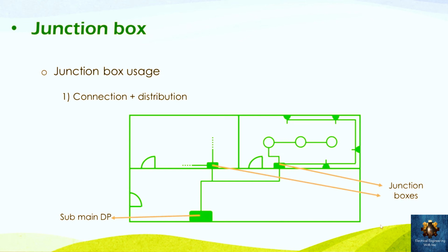Then we will go out of this box with some other conduits that are feeding the loads we have. Here one line and neutral inside one conduit go to the electrical sockets, and another conduit that has another line and neutral goes to the luminaires we have. So we don't go directly from the distribution panel to the loads, but we have an intermediate junction box. And in the same way, we go out of the second connection and distribution box with some other wires, as you see, and they are going through the conduit to the other types of loads.